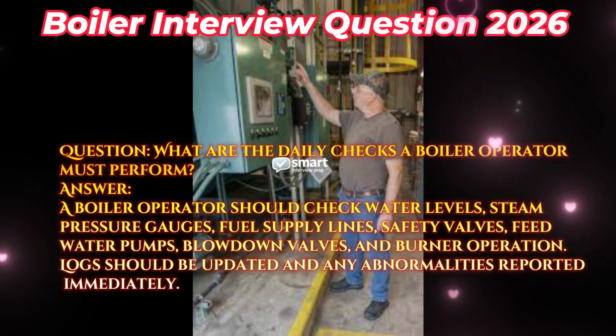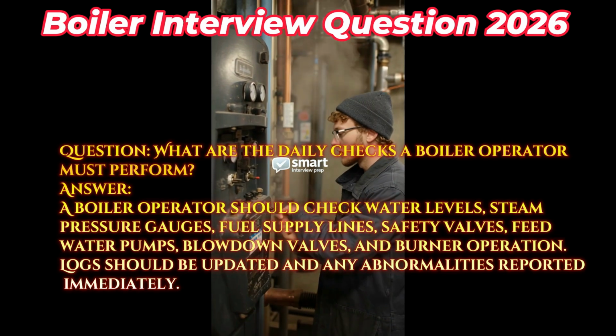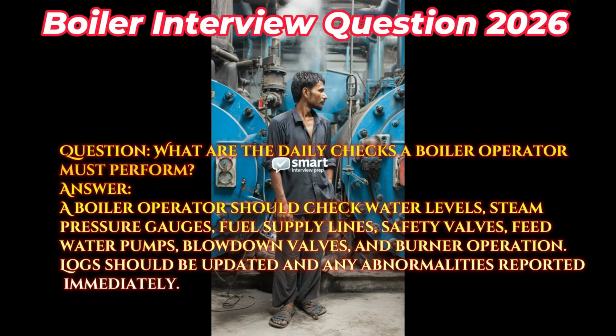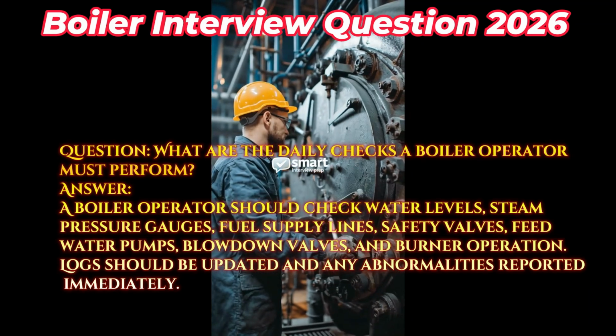Question: what are the daily checks a boiler operator must perform? Answer: a boiler operator should check water levels, steam pressure gauges, fuel supply lines, safety valves, feed water pumps, blowdown valves, and burner operation. Logs should be updated and any abnormalities reported immediately.